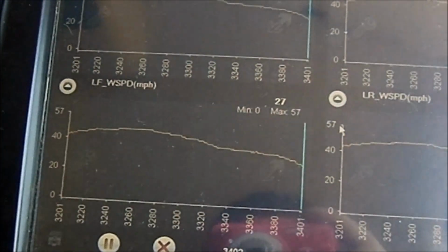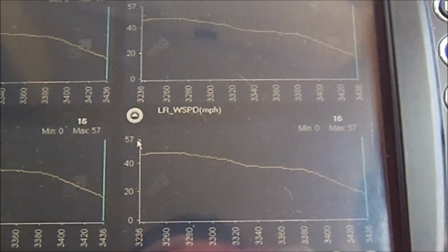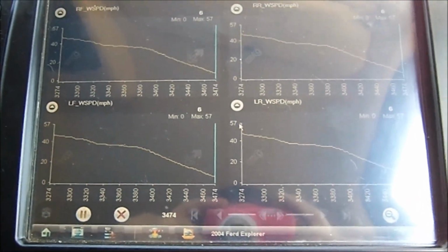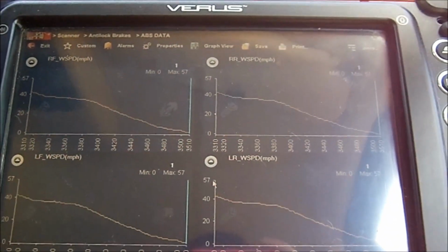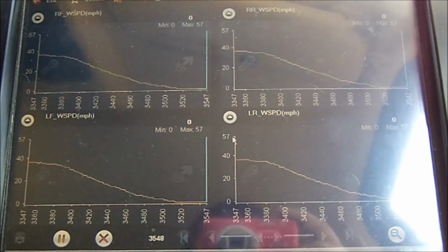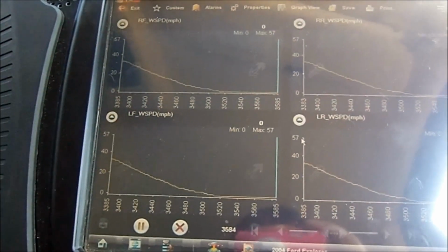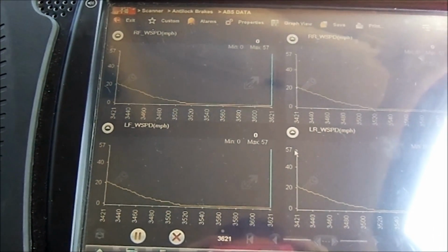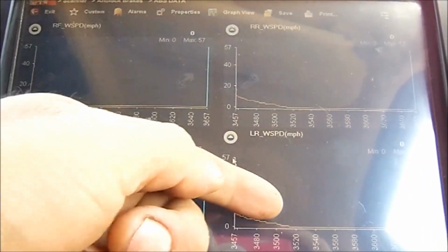These two on my left are the front speed sensors, and these two on my right are the speed sensor on the differential. It's a 3-channel ABS system, but we see that on the data screen it shows 2 parameters for one sensor. This is considered normal, but they should give you the same reading, both of them. The reading is coming from one sensor on the differential, and this is from the 2 front wheels. We are at 0 miles per hour. We have no glitches. I haven't seen anything out of the ordinary on the rear channel here.